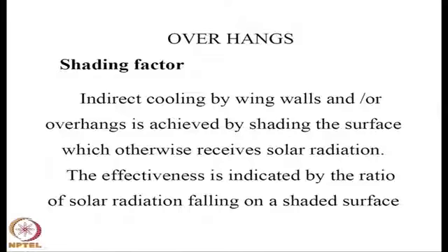So, you calculate as usual your utilizability, and 1 minus phi bar will be unutilizable multiplied by your HT will be the energy that will be going into heating the room to the desired level of, let us say, 20 C. Now, the shading factor.